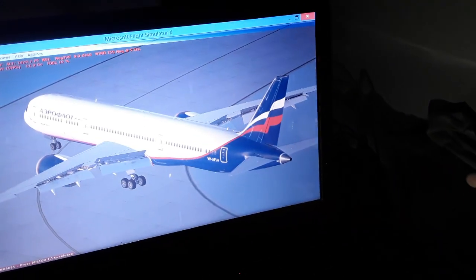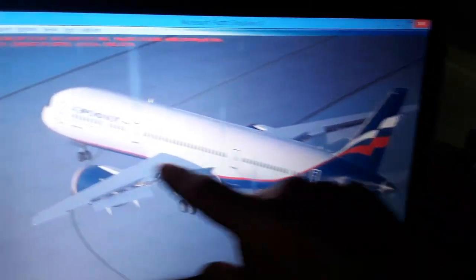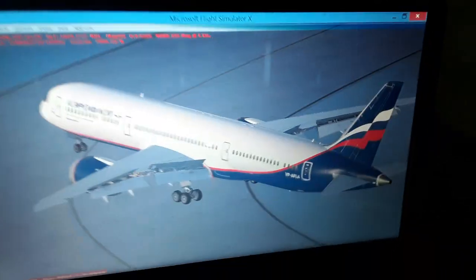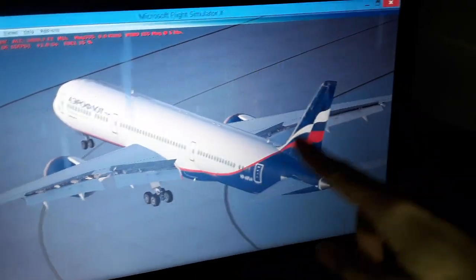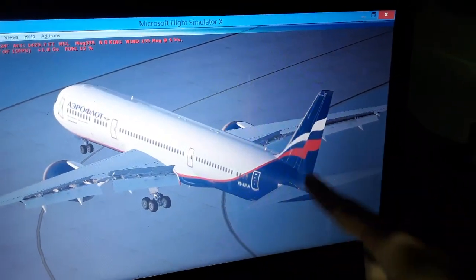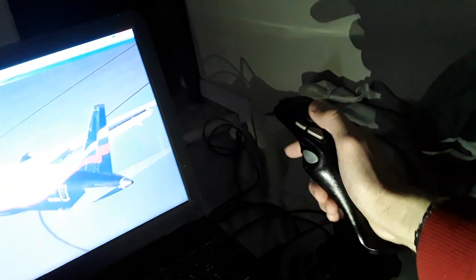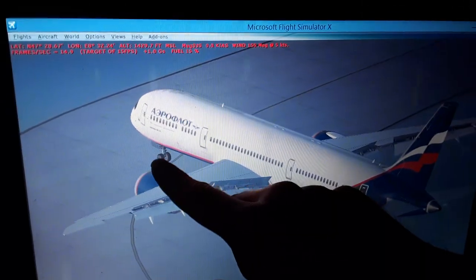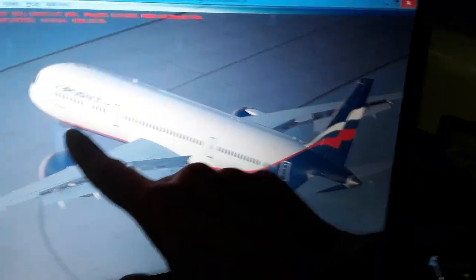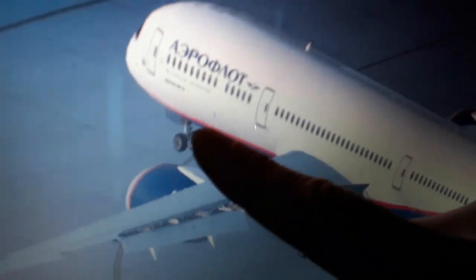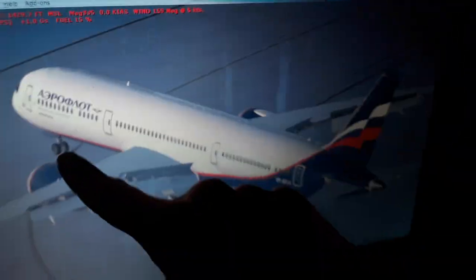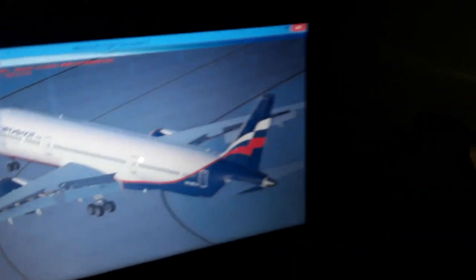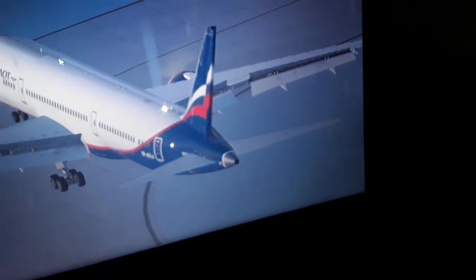It's automatically decreased by the computer: the deflection of the forward wheels is decreased from 76 to about 7.6 degrees above 45 knots or 70 kilometers an hour. So as we increase the speed for takeoff, we have more rudder, and at about 70 knots the forward nose wheel is locked to the 0 position, no deflection. So we have only the rudder aerodynamically effective at about 70 knots airspeed or 144 kilometers an hour for takeoff.